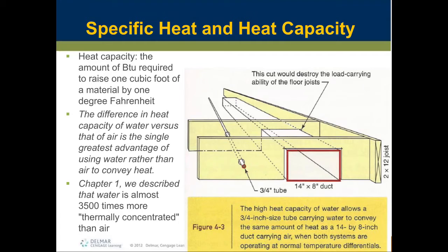So let's take a look at specifically how that is. One of the characteristics, and you might say, well, why in the world would we use water? Why not? Everybody uses air, right? Well, not exactly. In a commercial job, if we had to move air throughout an entire building, those duct systems would have to be so large. So in our commercial applications, we will utilize hydronics, or water. We'll move water around through the system primarily because of its incredible heat carrying capacity.